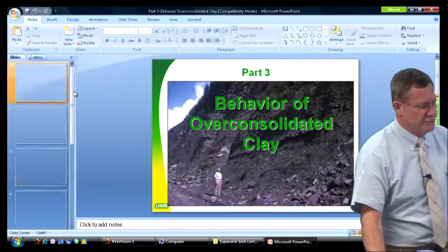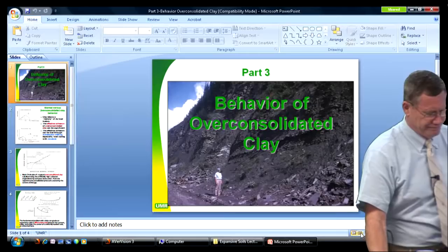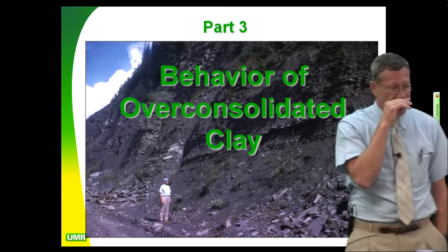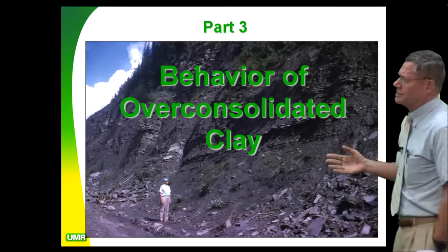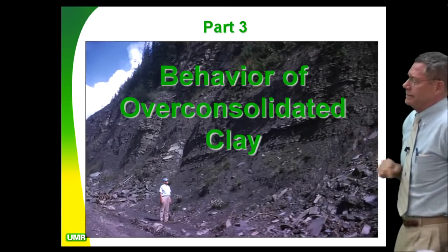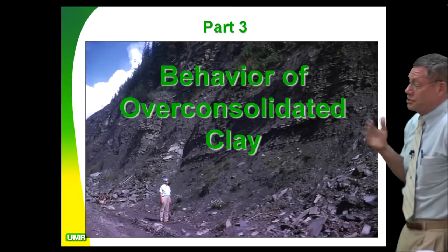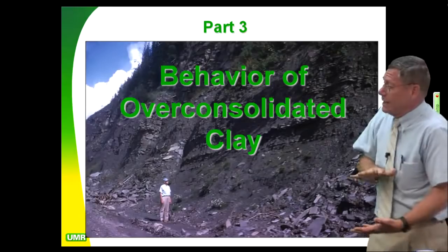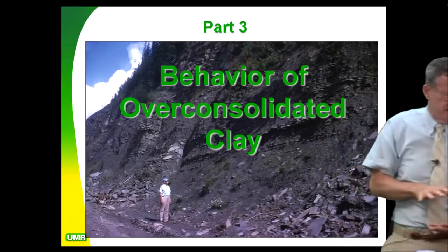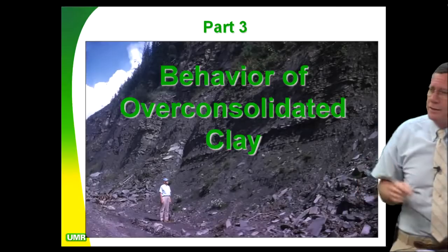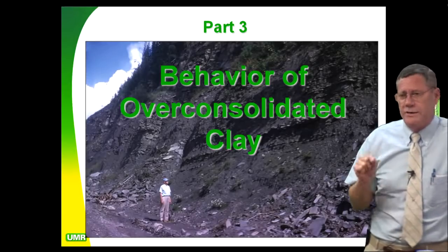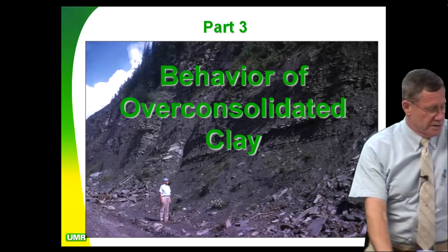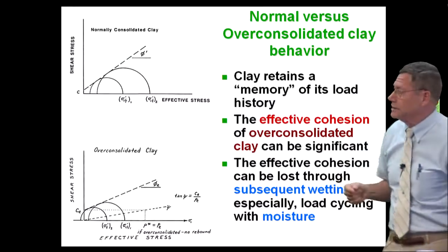Part 3. Part 3 is not real long, but it's real important. The biggest problems I've had in my practice have all been overconsolidated clays. I could teach a whole class called The Perils of Overconsolidated Clay. Why? The shales. Shales have been compressed tectonically. They've been taken down way in the bowels of the earth. And clay has a memory. It's intelligent material. You can't take too many clay mineralogy courses, because clay is always going to bite you in the behind if you don't understand it. And clay that's overconsolidated tends to lose strength with time.